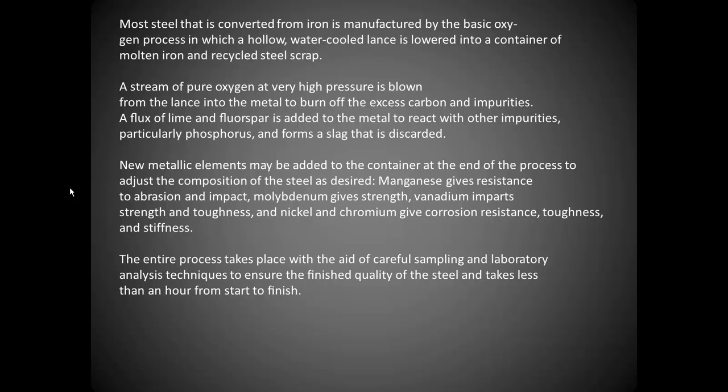And then they can add things to the material like manganese for abrasion and impact resistance, molybdenum to give it strength, vanadium imparts strength and toughness, and then we add nickel and chromium to give it corrosion resistance, such as stainless steel. And the entire process takes place with the aid of careful sampling and laboratory analysis techniques to ensure the finished quality of the steel, and it actually takes less than an hour from start to finish.